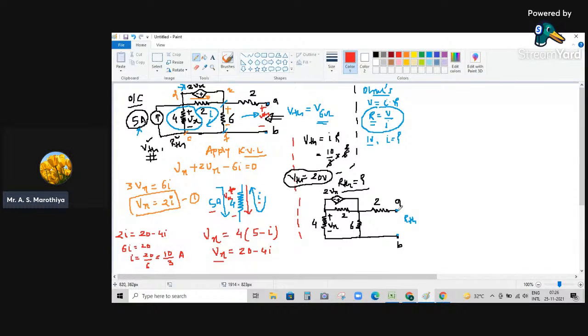First we need to connect a very small voltage source over here. Let us consider that this is plus and this is minus, and this value is say 1 volt. Because this is plus and this is minus, it has to supply some value of current in the circuit, and that current is say I. This current is going to flow in the anti-clockwise sense.